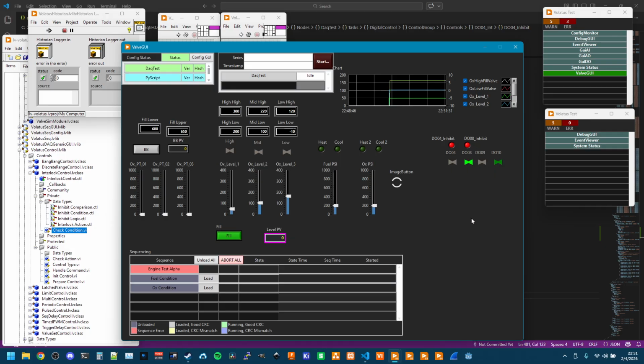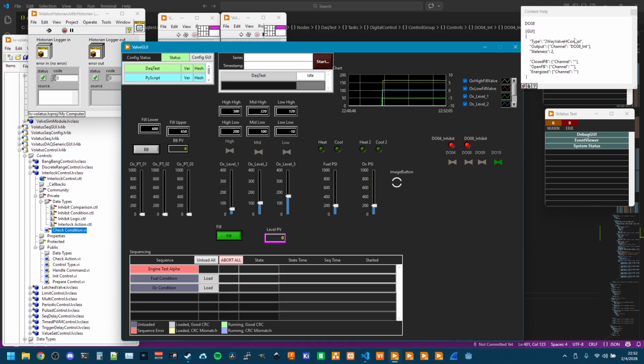While they're inhibited, notice that it's staying the bright green. That's the signal that it's not accepting the command. Right now I don't have good feedback that the command was received but ignored. So I set up some process values indicating whether or not the valve is inhibited to give some sense of feedback, and at some point maybe I'll come up with a way of better representing that it's inhibited.